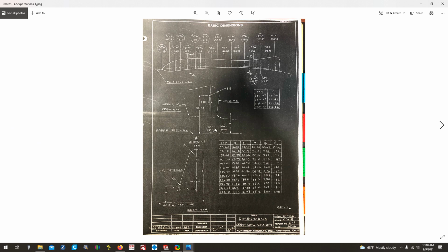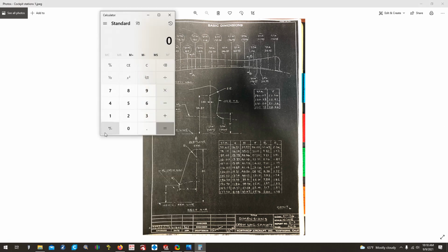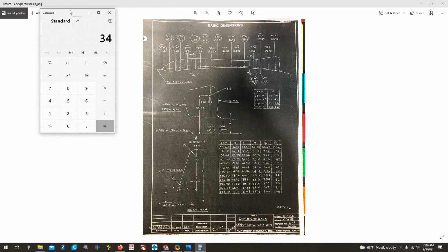We're going to kind of extrapolate. So here we're working at station 224.95. We know that this trailing edge extension here has a radius of 8 inches. And then we know 3487 is to the center line of that radius. So if we do that 3487, and it's too early for me to be doing math like that in my head, whoops, fat fingered it again. So 3487 plus the 8 will give us 42.87.